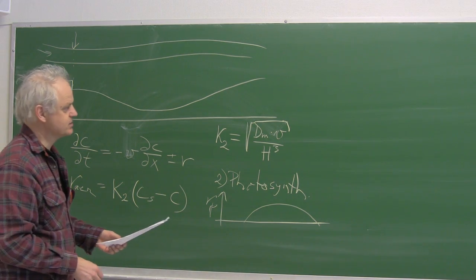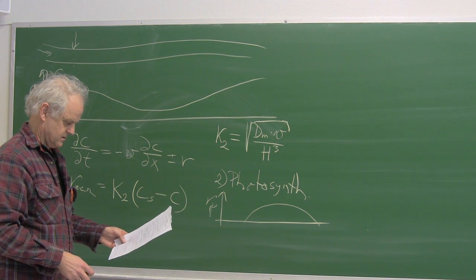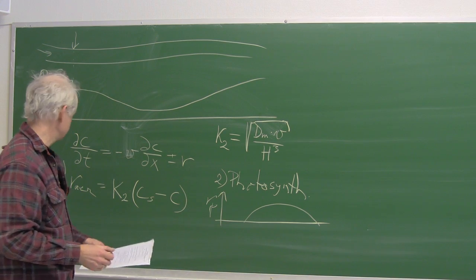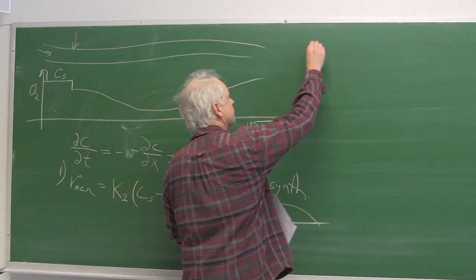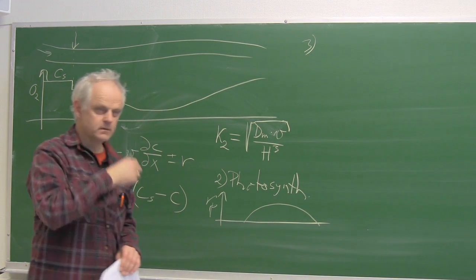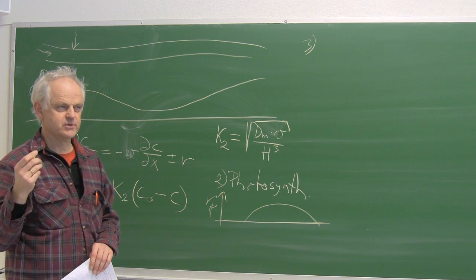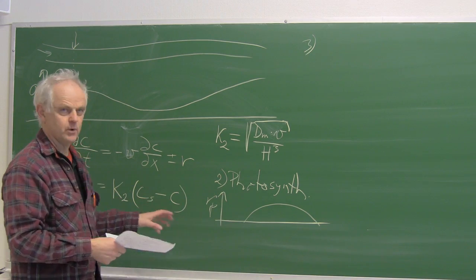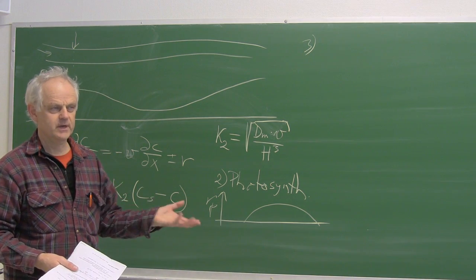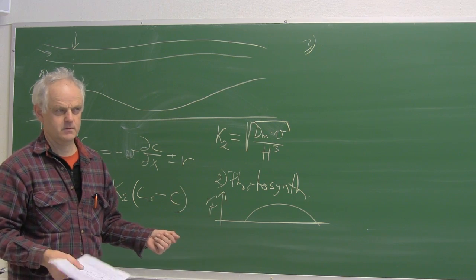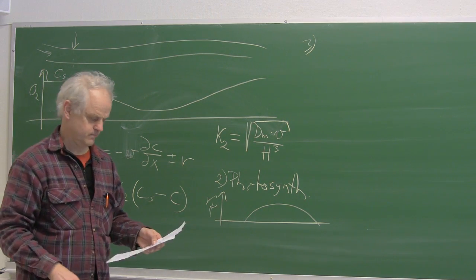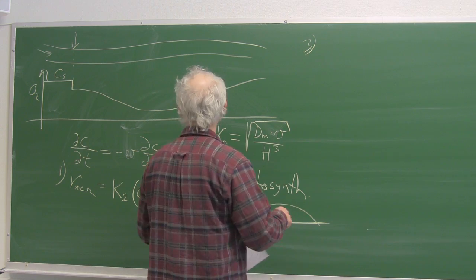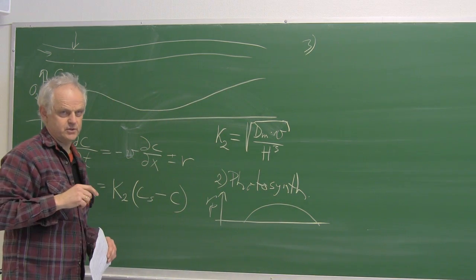As you can see in the notes, there is a formula and stuff, but let's not worry about that now. Let's just move on to a third process. And now we're looking for processes that have the opposite effect, that consume oxygen, because these are really the only ones that supply oxygen. What will consume oxygen? Microorganisms doing what? Eating the organics. Right. Eating the organics that come in the discharge.